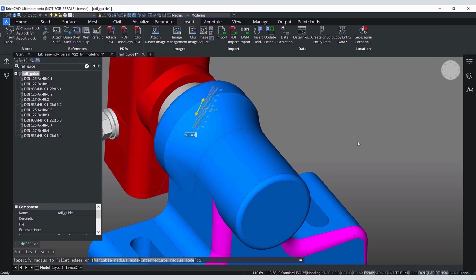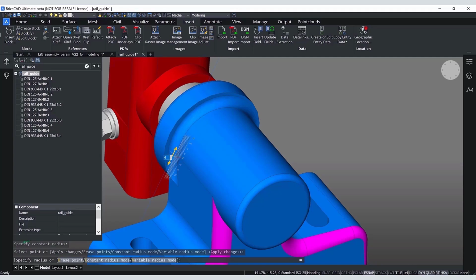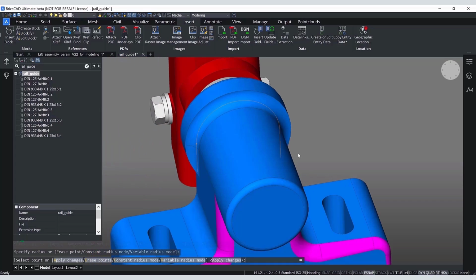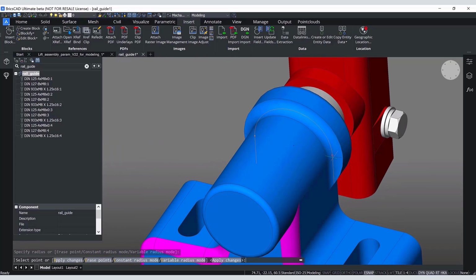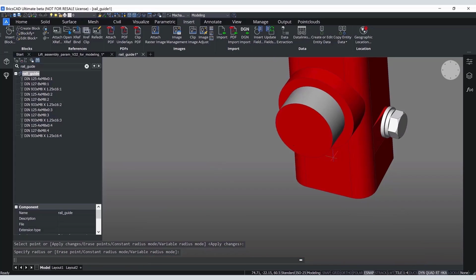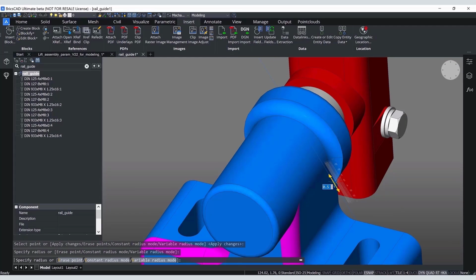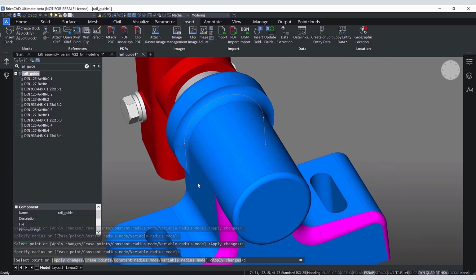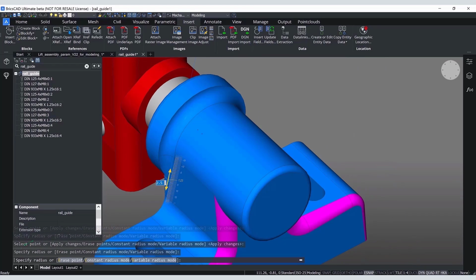Here we want to have 0 radius for the ends and some constant radius for the middle arc. How can we do this? If we set 0 radii for both sides, all radii become 0. So we need to firstly set intermediate radii for the arc ends and only then set 0 radii for the chain ends, like that.